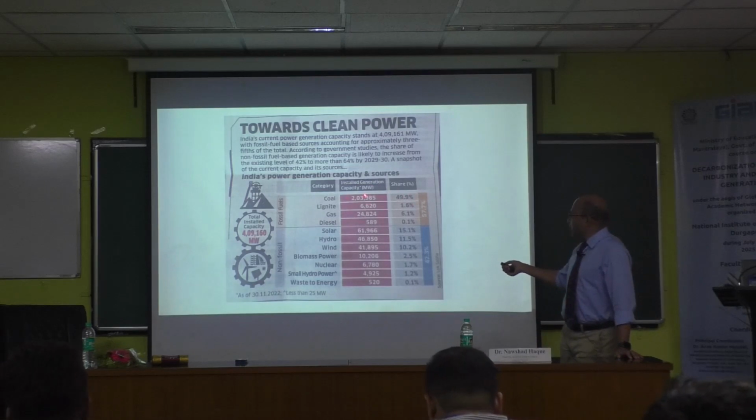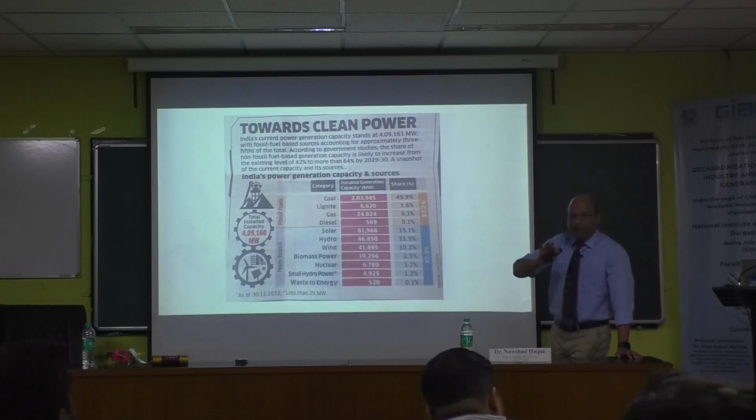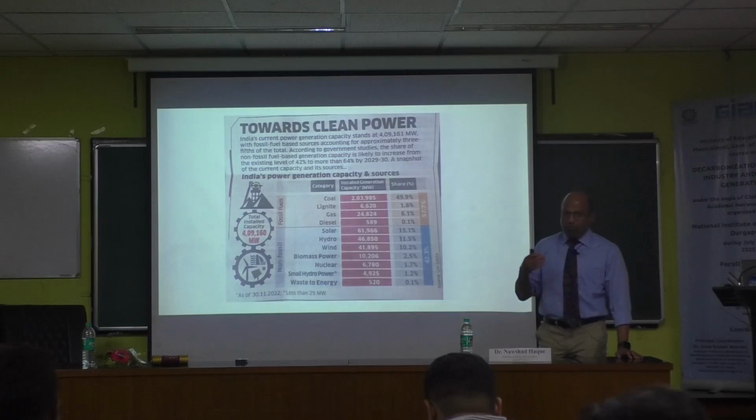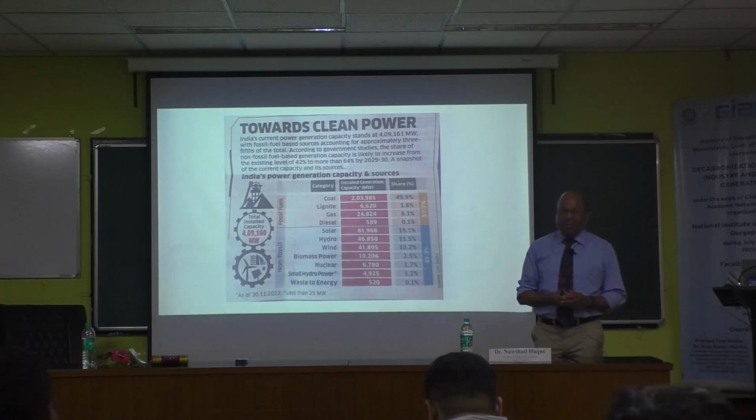But what I was saying is, say coal with that many megawatt capacity, and if you know the exact electricity sent out in million kilowatt hour units, that's fine. But sometimes we have to do generic calculations. So I say, just take the running time. Running time is usually 365 days, 24 hours, but you can never have that. Multiply 365 days by 24, it will be 8,760. That's the total. So 8,000 divided by 8,760 is maybe 90% capacity, 91%. Maybe that's too much. Maybe 80% is the right number, so maybe 7,500 hours or something like that.